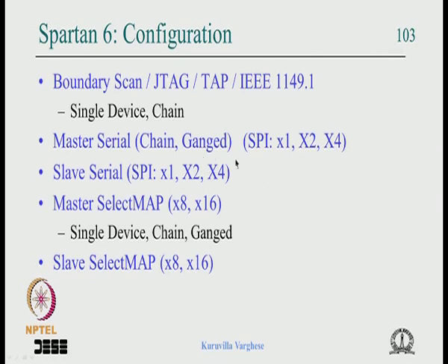Sometimes what is required is that the same configuration has to be applied to all the FPGAs. That means all the FPGAs are of the same type and are configured by the same bit stream, so they can be connected in parallel.